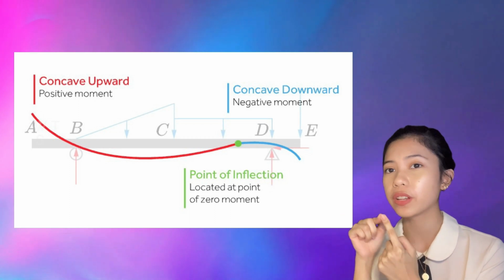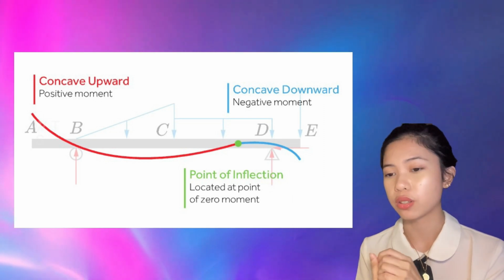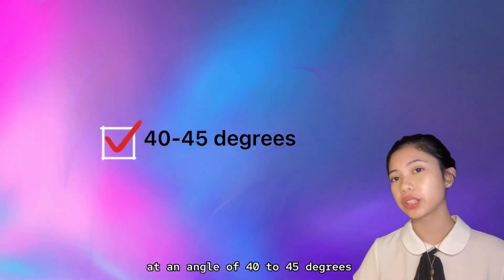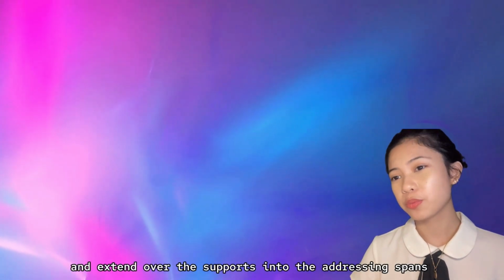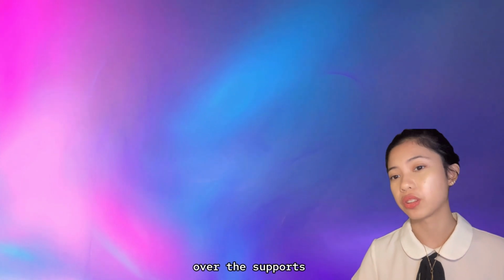So, yung point of inflection na yan is nagdedepende sa magnitudes of the loads as well as the end conditions of the beams. At this point, some of the reinforcing bars are bent up at an angle of 40 to 45 degrees. Ano ba? 45, 40, basta. And extend over the supports into the adjacent spans. The bent up bars serve to resist the tensile stresses over the supports.